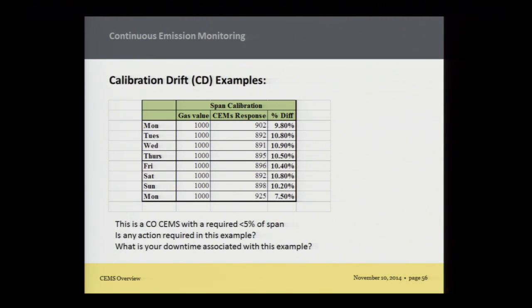If you recalibrate it the day you find it, you still have downtime? Or if you correct it? Yes, if you have a good calibration. Because most of them are usually set to run at a certain time, you're going to have 24 hours, 24 hours, 24 hours, 24 hours. If I come in and run it directly after, you might have just a few minutes of downtime, but what I typically see, if I've ever seen it go out on 5 times, is I've at least got 2 more hours because our auto cals ran at 5 o'clock in the morning, and the analyzer tech comes in Monday morning, and he says, "Oh, what you're saying is my analyzer is gone." And so you may still have 2 hours of out of control time before he goes and checks the analyzer. So it's the difference between when you got that cal and when you corrected it, whether that be 2 hours or 24 hours.